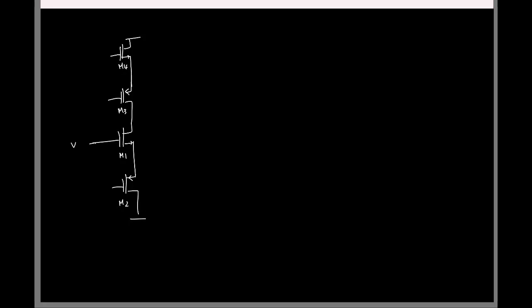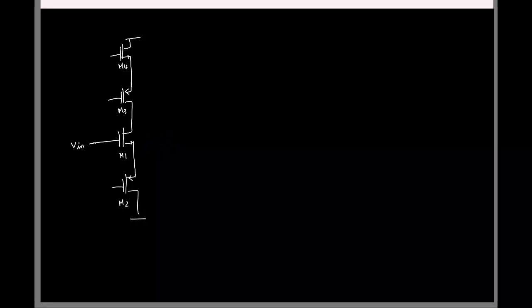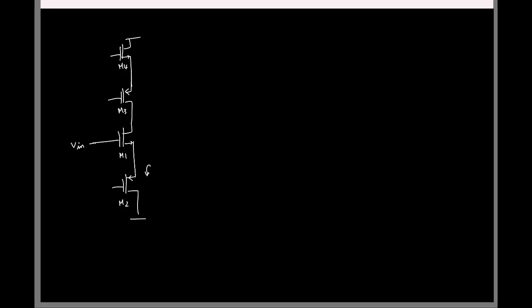The second question was basically something like this, where you have an incorrect cascode. This was M1, M2 probably. Again, the first part was to find the short circuit GM. This was the input. One common thing I found was you guys wrote that the current in this transistor is GM Vin. That is not correct. Remember, the current is GM VGS. It is not just GM times the gate voltage. So what is the impedance looking down? It's 1 by GM of the transistor M2, 1 by GM2.